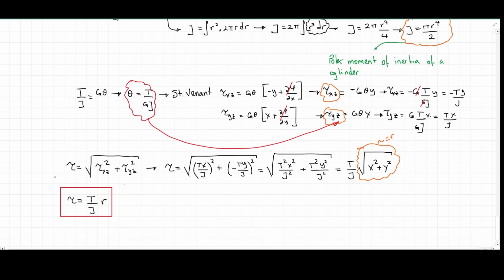So we used Saint-Venant to determine the maximum stresses found on a shaft of circular section with a torque applied. At the end, we always want to find stresses so we can compare them to reference values, such as the yield stress.